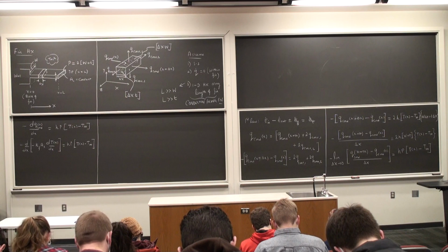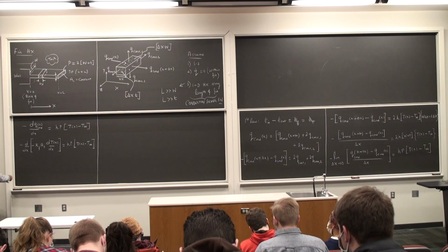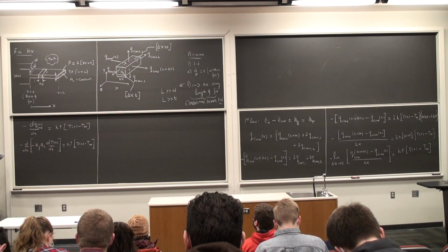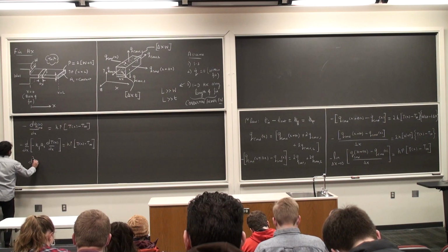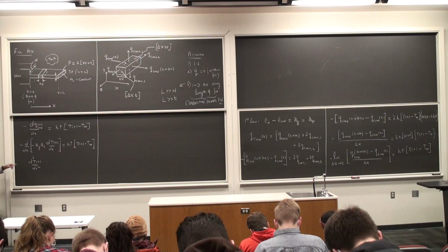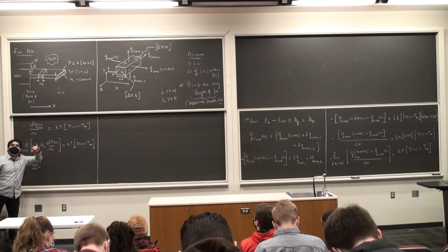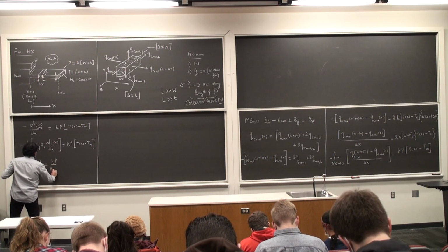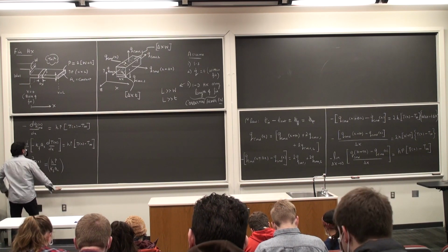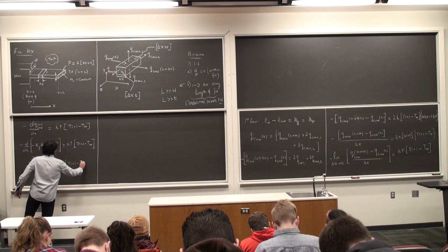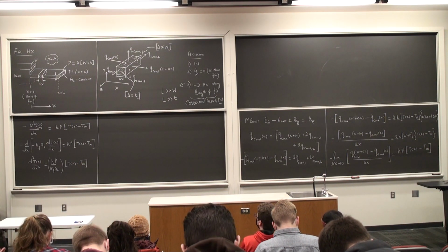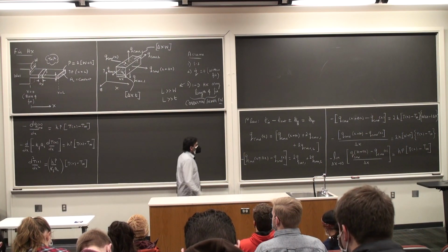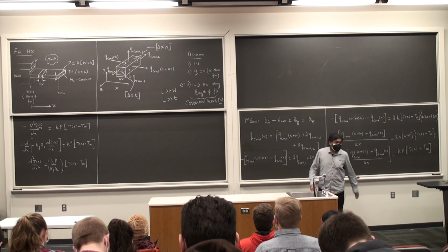K is a constant, area of cross section is a constant. Take all those constants out. Look at the way I'm going to write it. d by dx of dT by dx is d square T by dx square. Okay, so second order. I'm going to take this k_f and then A_c and bring it onto the denominator there. Okay, so that's going to be h P by k_f A_c times T of x minus T infinity. Alright, so we are so far so good, almost there.